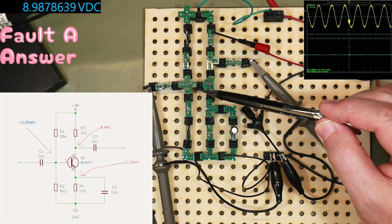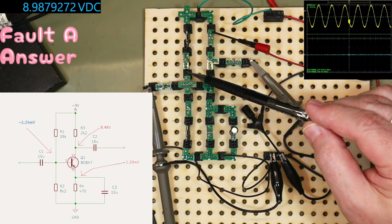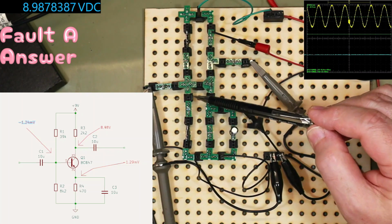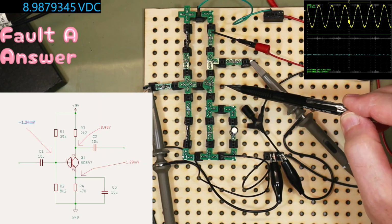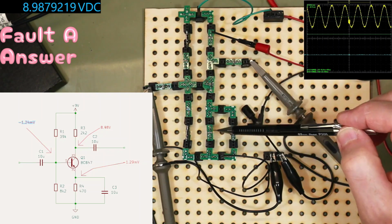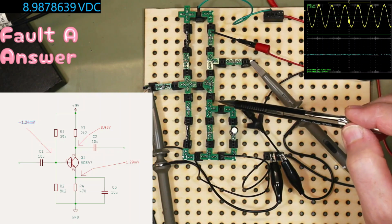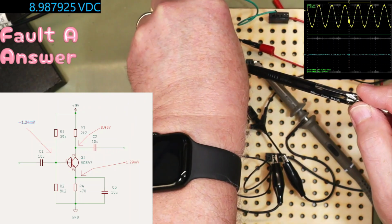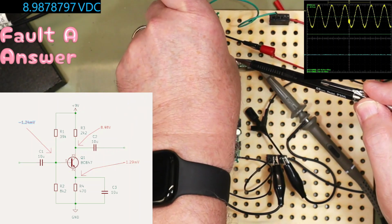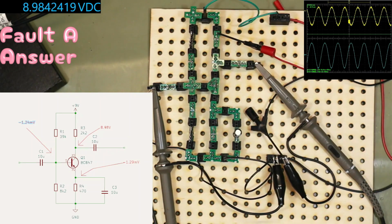So why is there no current flowing? Well, there's no current flowing down here. R1 is open circuit, so the base is being pulled down by R2, no base current. Transistor is fully off, therefore no current. No current flowing, can't be any output. Simple as that. And to prove it, I'll just put this link back where it should be, and it's all hunky-dory. We're back to where we should be,